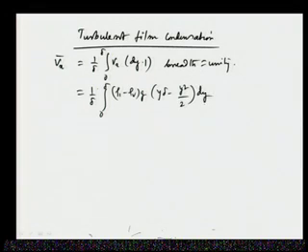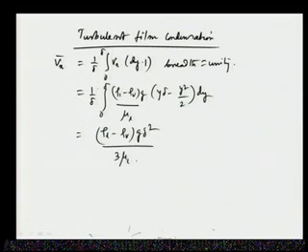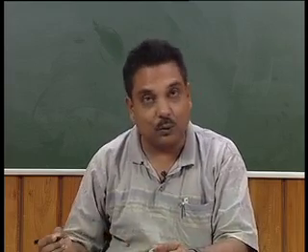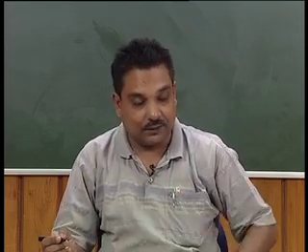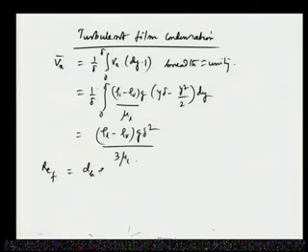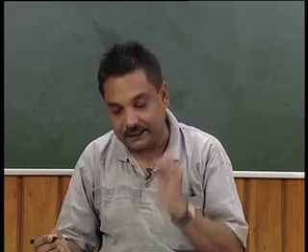So, for this case it is becoming divided by mu L, and this becoming rho L minus rho V, and then g into delta square by 3 mu L. So, this is becoming the average velocity along x direction of the fluid, and so Reynolds number we know is given as, if we say the Reynolds number of the film, Re_F, where F indicates the liquid film, that is hydraulic diameter into V rho by mu. So, dH rho Vx bar by mu L and rho L, because we are considering the liquid.